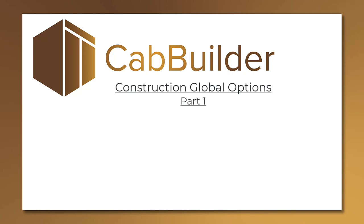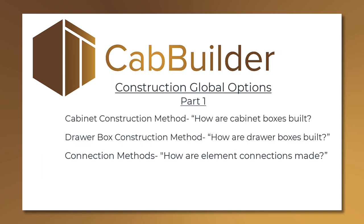This video will tackle the construction global options by setting up connections and a drawer box construction. Construction methods answer the question of how cabinets are built. The answer encompasses overlay reveal settings, grain directions, facade orientations, drawer box dimensions, connection tolerances, and other manufacturing standards that differ from cabinet shop to cabinet shop.